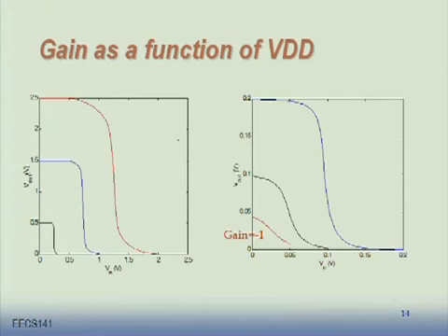interesting things happen. So what happens with this gain as we scale the VDD? What is very interesting, it's very robust. It actually gets better as I scale down the VDD. Why is that? And particularly for these short channel devices, it gets significantly better. Why?